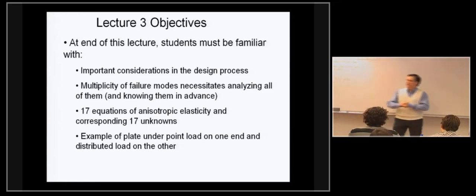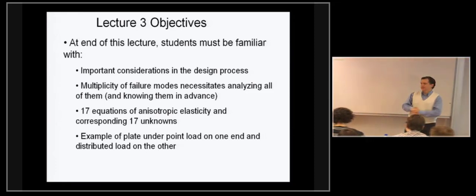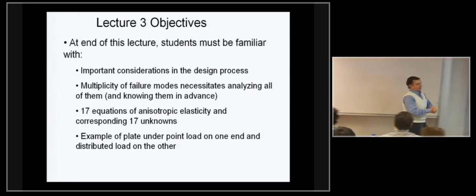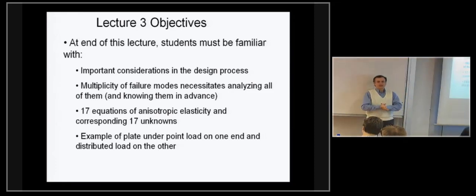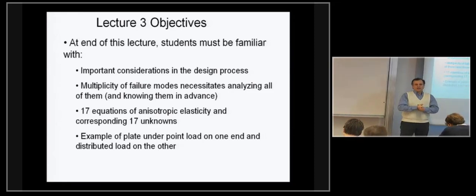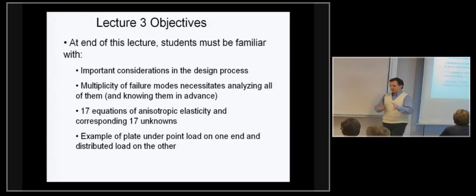Today we'll also do engineering by compromise and voting engineering. You'll see if we can design something by voting and democracy, whether democracy is a way of designing structures, which we'll do in a little bit. We finished the classical laminated plate theory in terms of being able to calculate, for a given laminate, the stiffnesses, and I use the plural because we have the membrane in-plane stiffnesses and the bending out-of-plane stiffnesses and coupling.